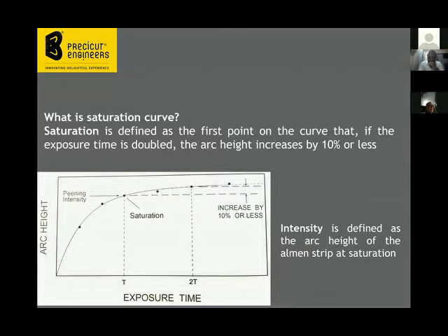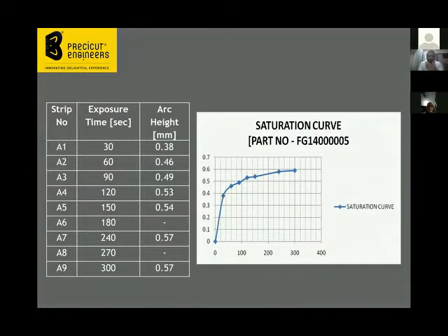So here you have to understand that the first point, the point T at which we achieve this saturation, is called the 100% coverage point. And when we say 100, 150% or 200% coverage, we are just increasing the cycle time by that factor. So a 200% coverage, which I had shown earlier, frankly means the cycle time equals 2t if you refer to this diagram over here. If it says 150%, then it will be 1.5t and so on. So this is one of the typical graphs which we had plotted. I won't go into much discussion because we had seen this earlier also.